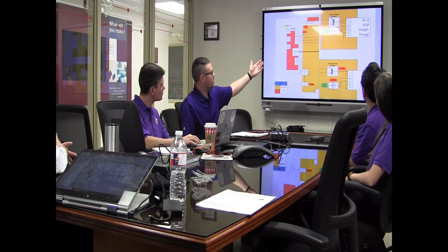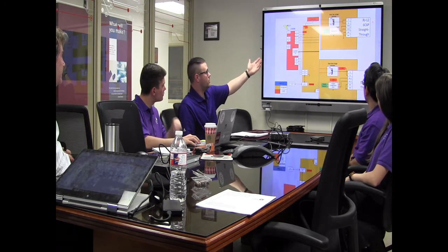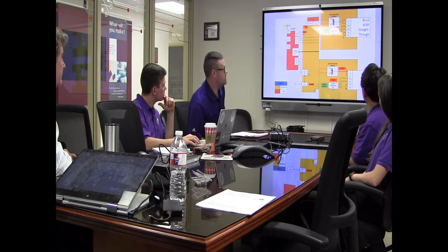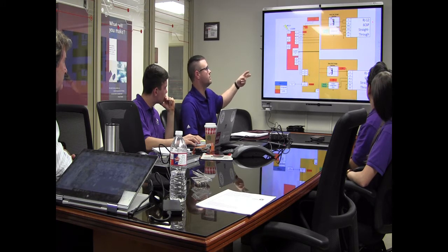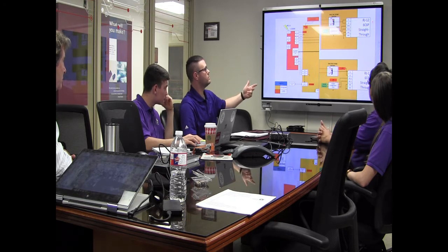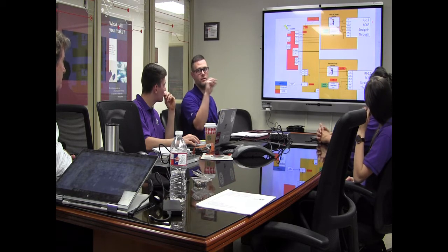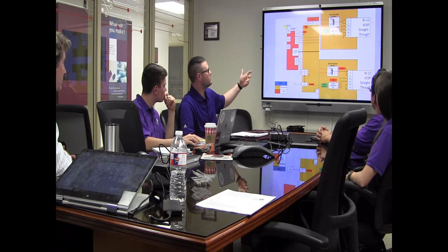And then we also have, so each one of our outputs. On the top part is kind of an exploded view of our RJ12 6-conductor, 6-pin straight through RJ12 line. The top two conductors are conductor 1 and 2, or V1 and V2, and you can select the voltage that you're sending to those with a little shunt bar. You can select either 12 volts or 5 volts. And then the middle two lines are PWM 1 and 2 that are low side switched to the DMN2041, and then bottom two are ground.